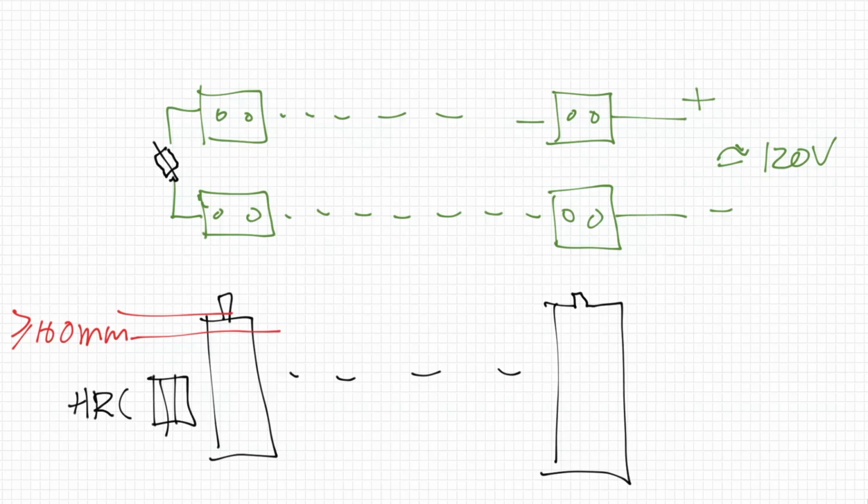It could be inside the enclosure because it is only for maintenance. It's not part of a shutdown procedure. It's part of a maintenance procedure. You could even just put a fuse in there. You don't actually have to have the isolation, but it's very good work practice to do that. So yeah, hopefully that explains, Nathan, how you can include midpoint overcurrent protection and isolation within an enclosure where there is explosive gases.